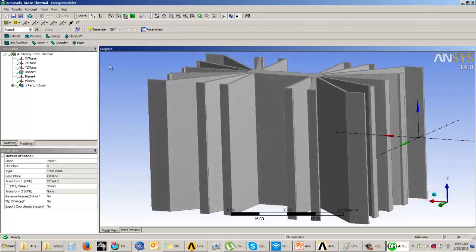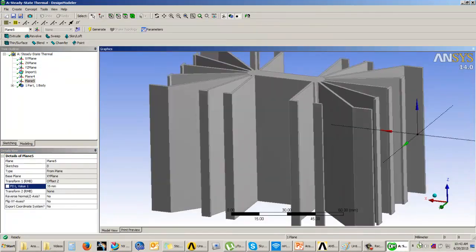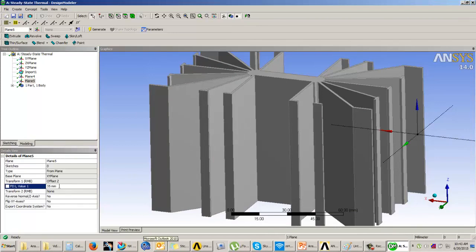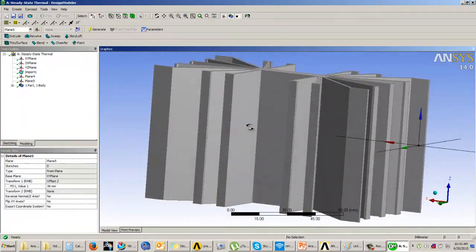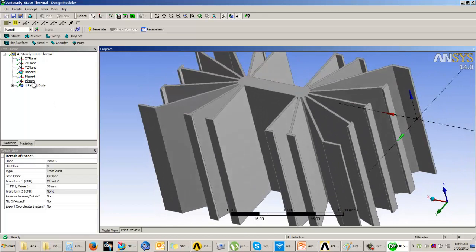In this case, you can use your edge tool selection. Select any edge over here. It is 76, so half of 76. You can find out the value. So this value is not 35. So half of 76 would be 38. So now we have both the planes.